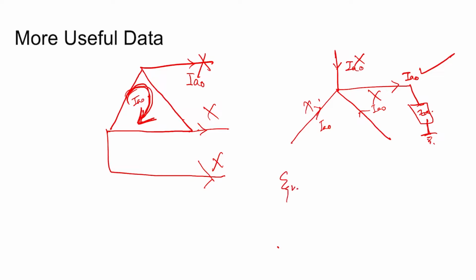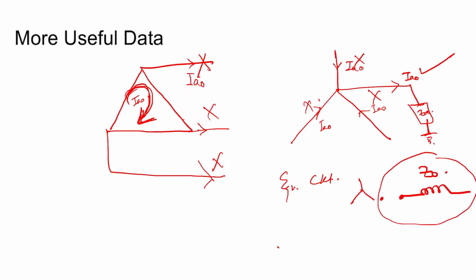So if I am asked to draw the equivalent circuit for the zero sequence component for a star connection, if this is the zero sequence impedance, then in the line it cannot flow, so this should be open circuit. If this is star grounded, that is the neutral is grounded, then in the line the fault current can appear in the zero sequence circuit.